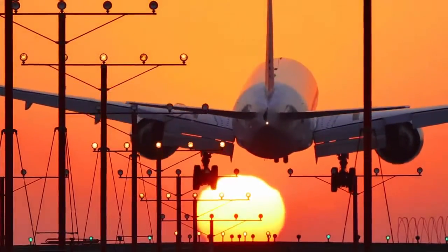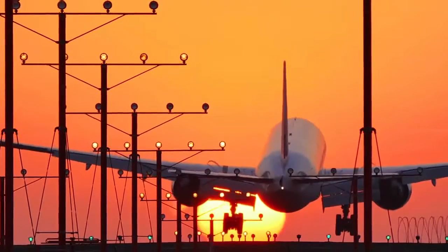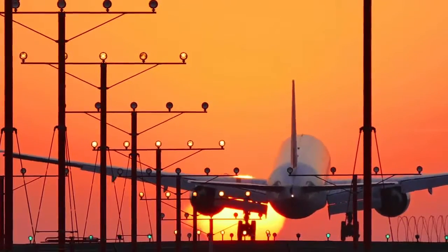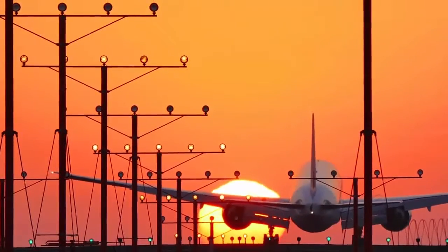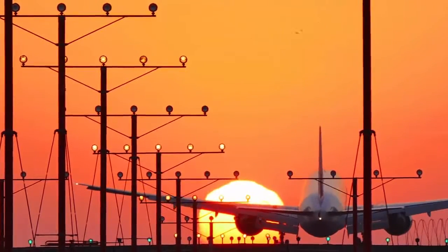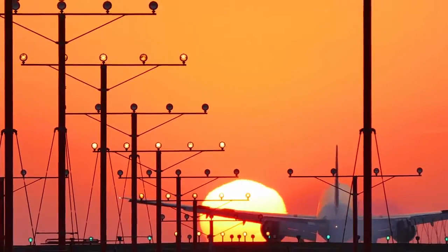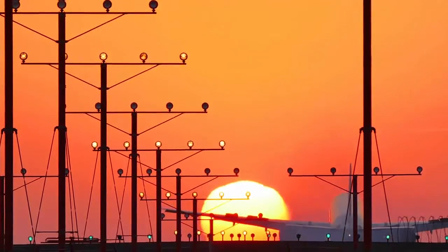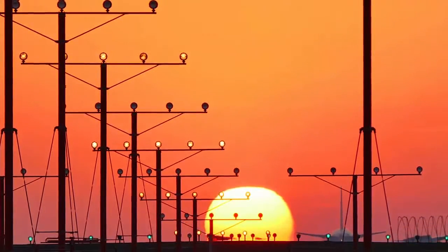This is a real-time adaptive process, allowing for rapid and reliable phased array UT inspections on such complex geometries. This video will illustrate how state-of-the-art phased array units controlled by UltraVision software can be used to apply the time reversal technique to improve coverage and detection capability of ultrasonic beams for various CFRP geometries.